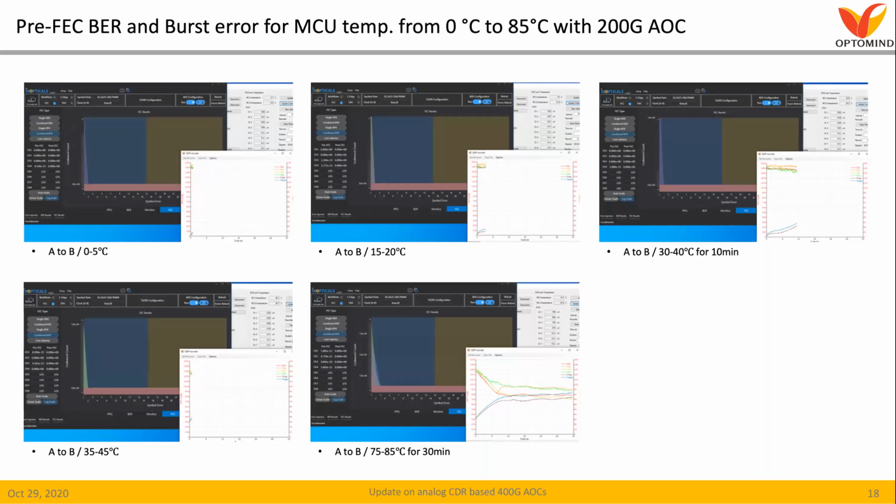We maintained the measurement for 30 minutes at 85 degrees C to see any significant change of behavior of RSSI at highest working temperature, but the result showed very stable curve for all 4 channels. That means implemented OSA has a very good immunity in thermal expansion for full range of operating temperature.